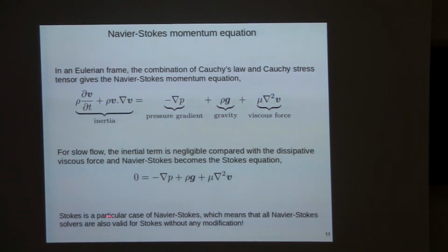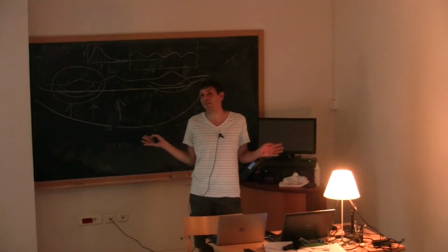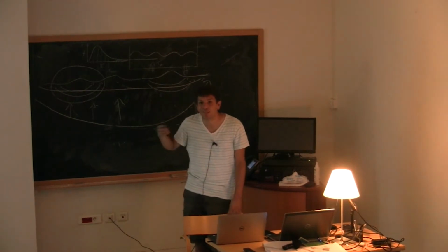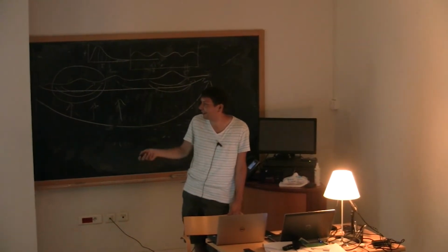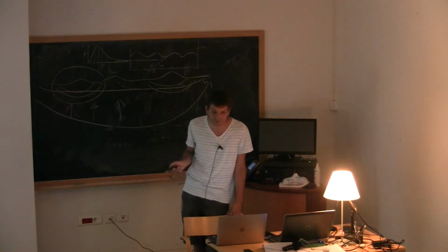Yes. So something important to say also. Most of the numerical tools you can find, commercial tool, open source, soon we will say a few words about that later, they are designed to solve Navier-Stokes equation. You download OpenFOAM, they solve Navier-Stokes equation. You use ANSYS Fluent, they solve Navier-Stokes equation. But it doesn't mean that if you want to solve Stokes, you need a different solver. You can use the same solver. It's only that the inertia term will be negligible. It will not appear in your solution. Stokes is just a degeneration of the Navier-Stokes equations. Okay.